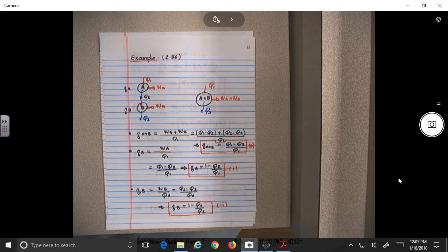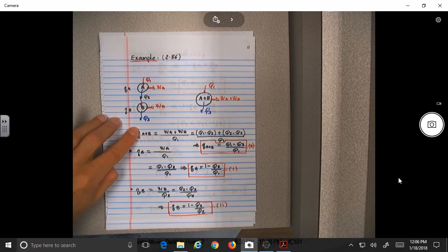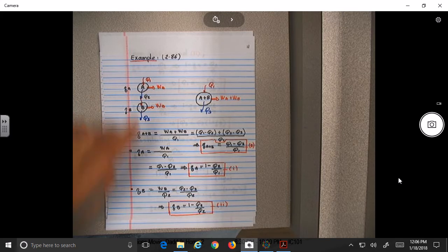Okay? In this case, with those temperature changes, Q1, Q3, will you be able to generate that amount of power? I mean, you could if you had an engine whose efficiency was 0.51, no, 51%. However, what is the efficiency of an engine generally? It's 30%. So if you had Q1 and Q3 fixed, what would be the only option for you to be able to provide that amount of power?